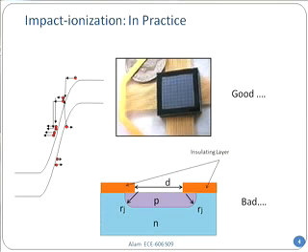Now, this is a very important problem. Of course, in technology, there are places where this effect is actually used to great advantage, and sometimes it is bad. There's always good and bad. On the top side, where I say good, these could be imagers, where you reverse bias a diode just before the impact ionization point. So it hasn't really been impact ionizing a lot.